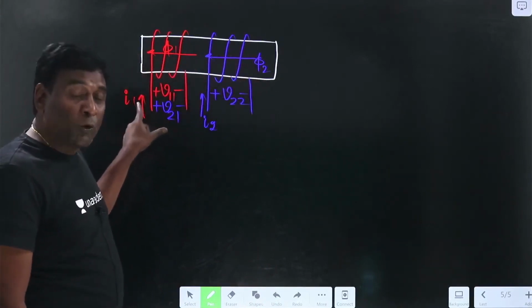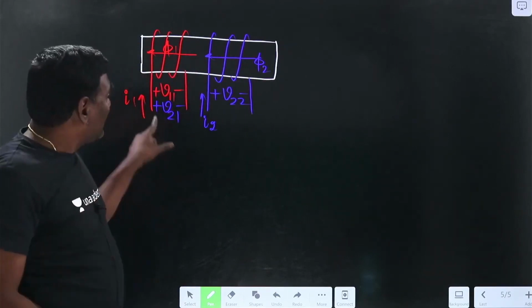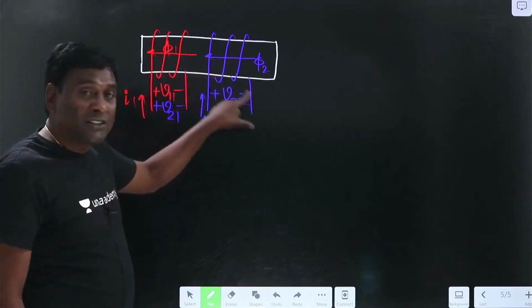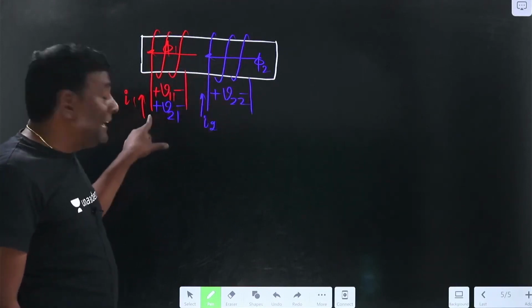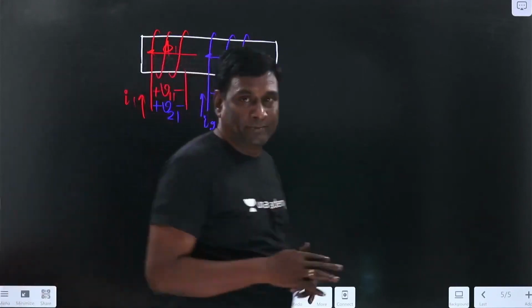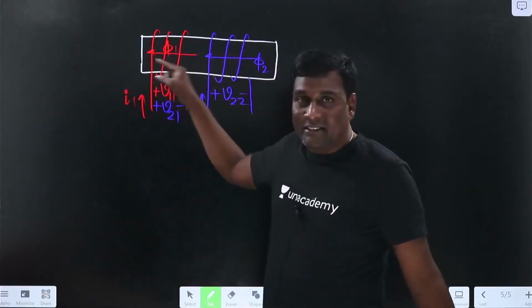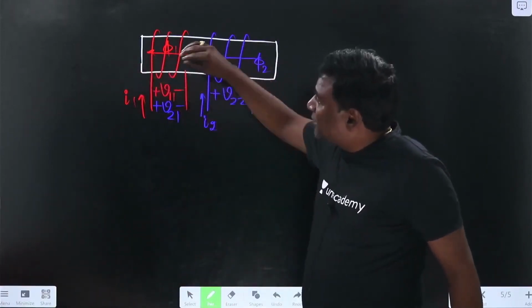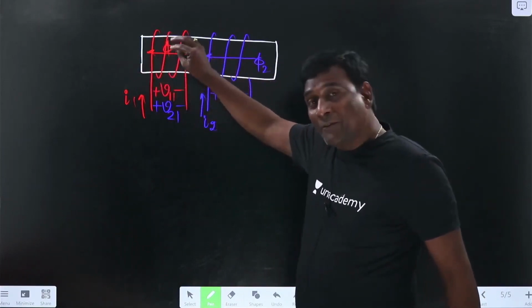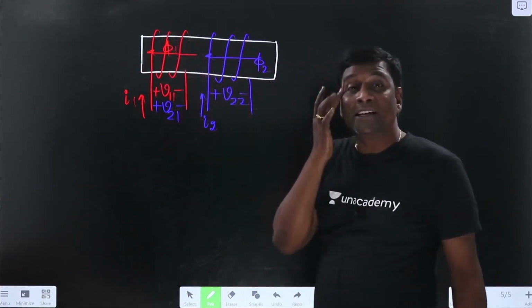That voltage should be increased. Or that particular induced voltage because of second coil current should aid the self, because self is also in this direction and this particular flux is also in this direction. Because of existence of phi 2, net flux here is going to be increased. Net flux is increased, meaning that net induced voltage has to be increased.